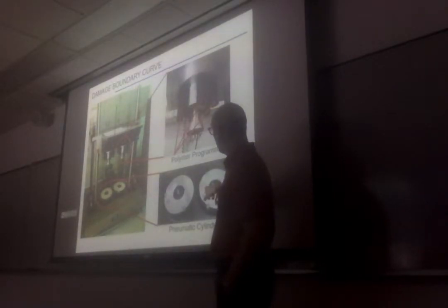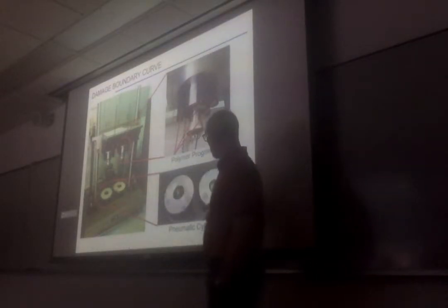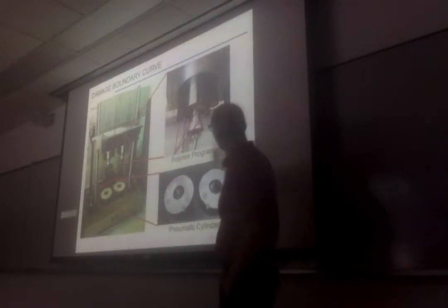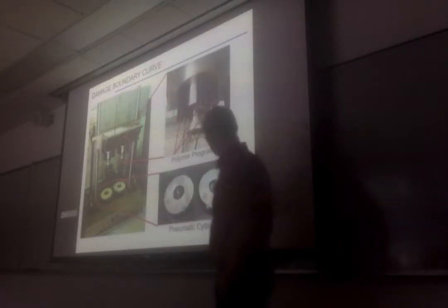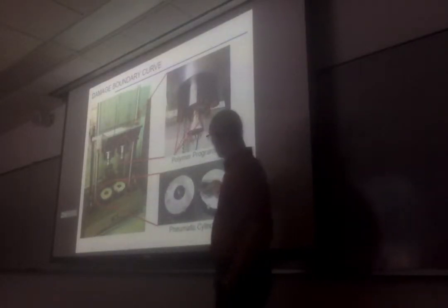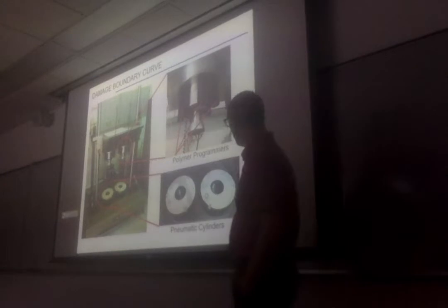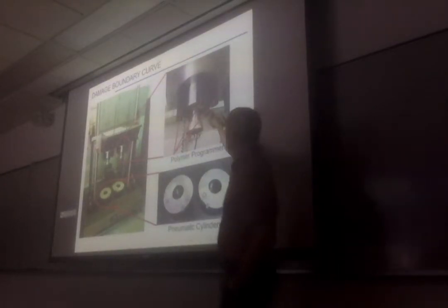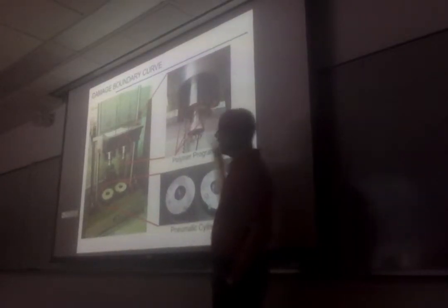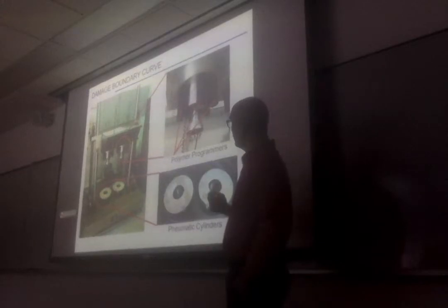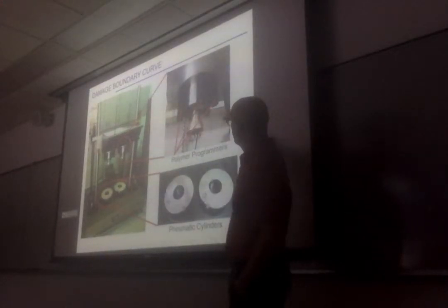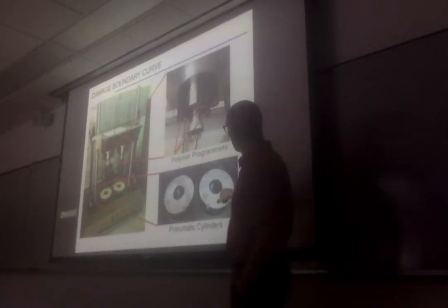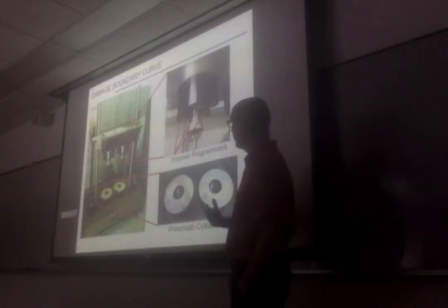I'm going to talk about it a bit later. If there's no air in here, those pistons are down, and the impact occurs on those polymer. The plunger will go in the hole, and you see those circles all around these felt pads. They come from the impact of the polymer. So that's the first series of tests we're going to be running, dropping these, and you have impact directly on those plastic polymer. You create half-sine types of impact.